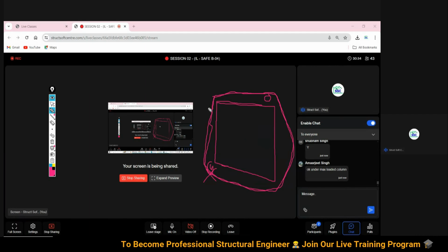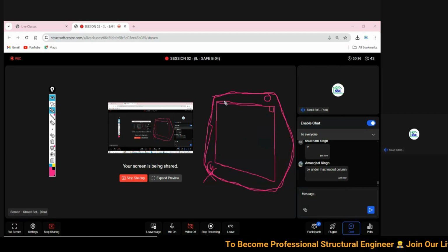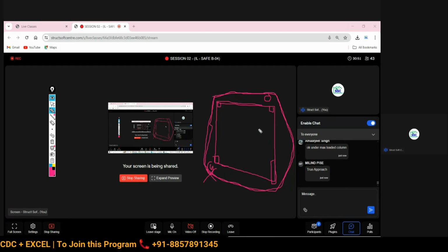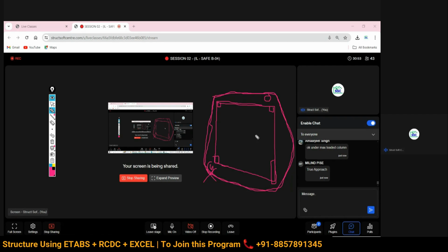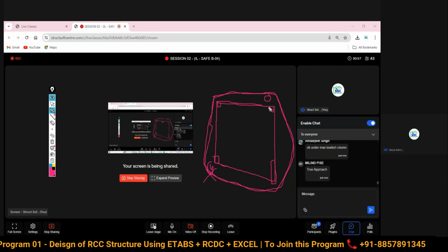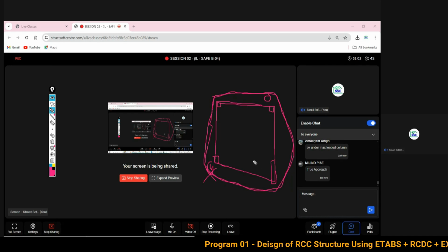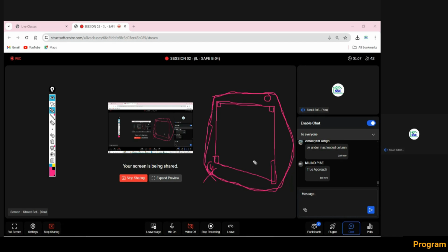After the modeling, suppose this is my building, and one column is coming here, one column here, one column here, and one shear wall is coming here. So what will the structural engineer do? Okay, these are the columns, so at four corners you are all suggesting to do the exploration. Yeah, that is correct. As per our structural configuration, columns are coming at four corners, plus the geotechnical approach is to recommend performing the soil investigation over the proposed area at the four corners, plus at the center, so that we can predict the entire area that is going to be covered.